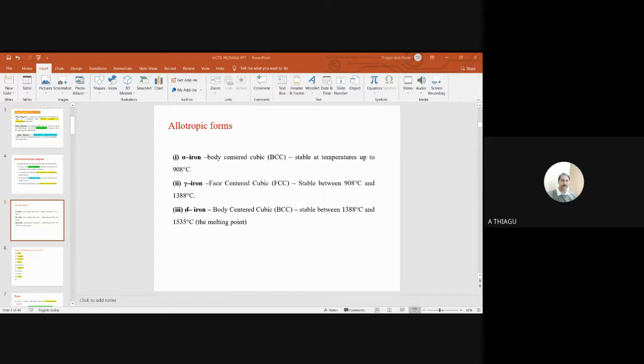Okay. So this is the reaction that happens in a particular location, available in the iron carbon diagram. You can find the correct area. Now quickly move to the last section, eutectoid. Eutectoid is nothing but one solid S1 transforming to produce two solids, S2 plus S3.